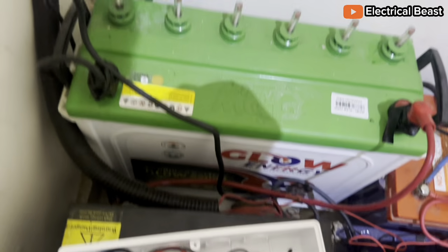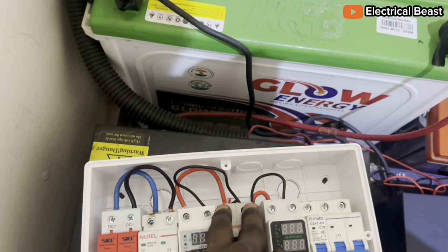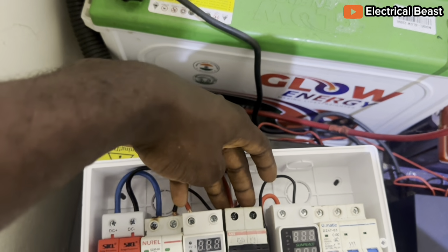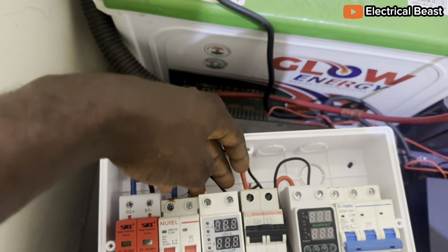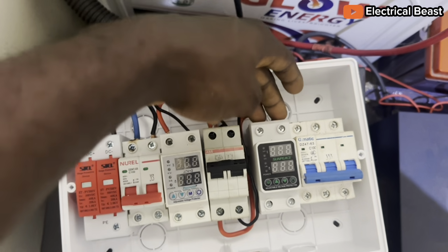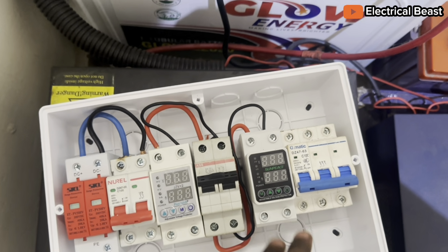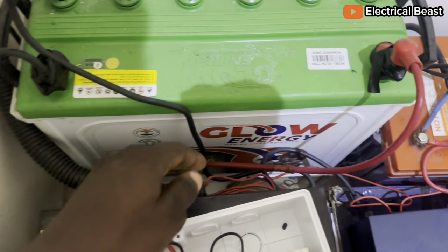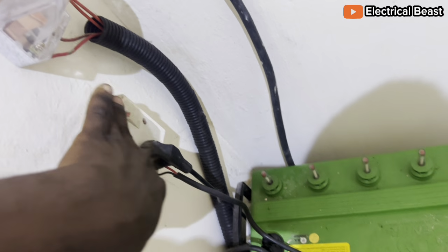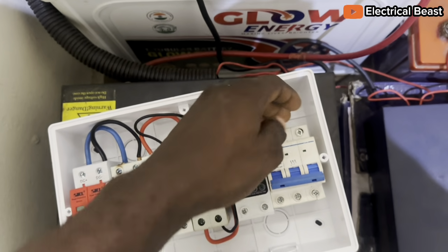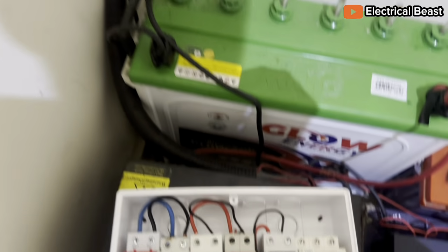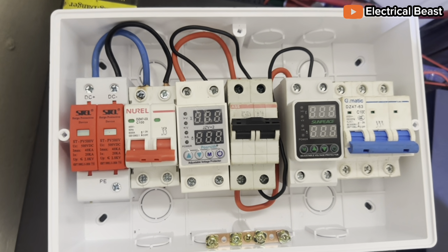Then again, this is the AC input. Normally, you connect this one first of all to this part where it loops to the AC surge protector. Then the output is connected to this AVS. Then the output of the AVS goes to the inverter, but here it is going to the inverter directly. Then the output of the inverter, which is this wire, goes to this changeover. Before it gets to this changeover, you're supposed to connect it to a breaker, whether live and neutral, or sometimes live or neutral. Then the output goes to the changeover where you can switch. So that's all for that. This is the solar protective kit.